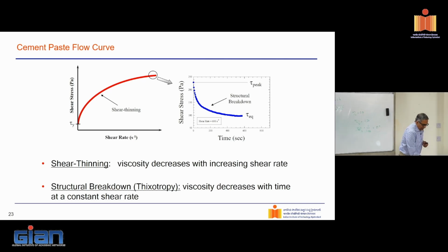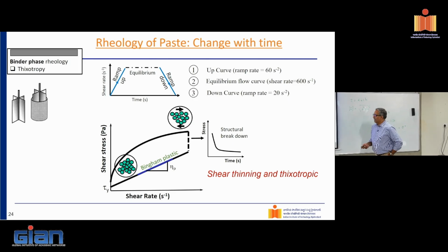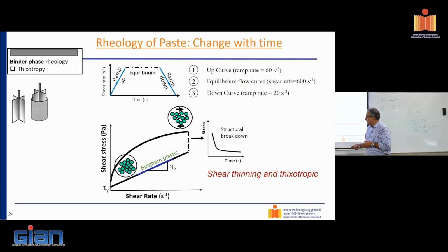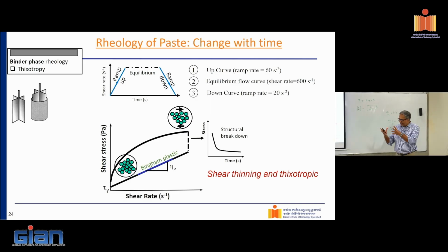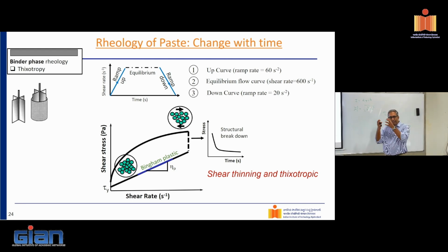Now, what causes this? One can get into the understanding of the material. We know that cement has a skeleton that's formed inside. That's what gives us this yield stress here. It has a shear thinning behavior because, once I smash the structure, the material basically forms, if you could look inside there, these flocks. Basically, several particles stick together, they form these flocks.